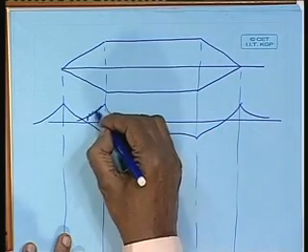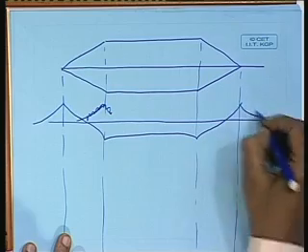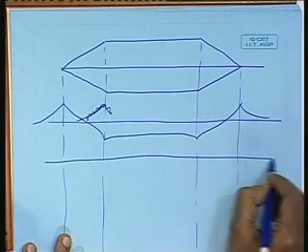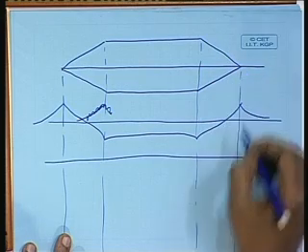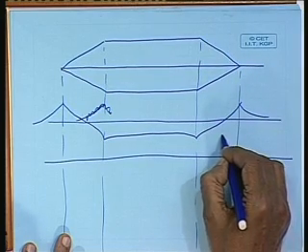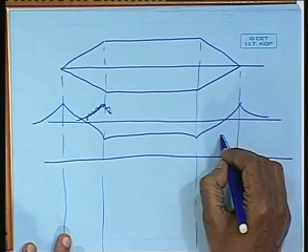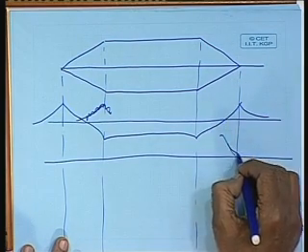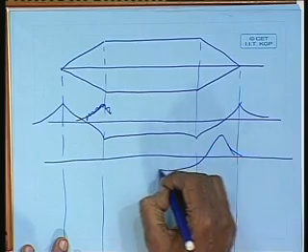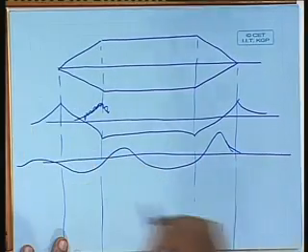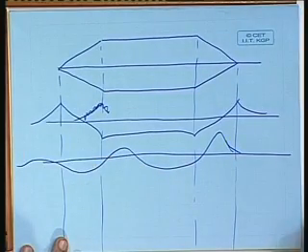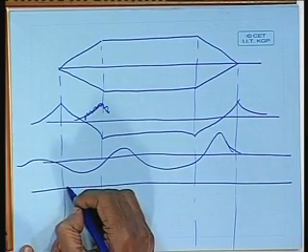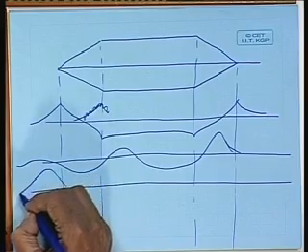That is the basic pressure change that stays. Apart from that, there are 4 wave systems. The one that is due to the forward end will have a predominant wave crest generated due to the forward discontinuity, and it may look something like this. Okay. Then, as you have seen, there will be a wave system due to the aft end, which may look something like this.